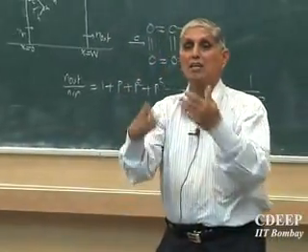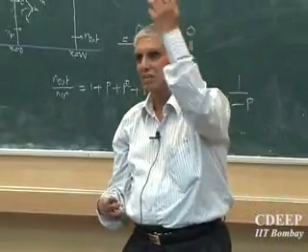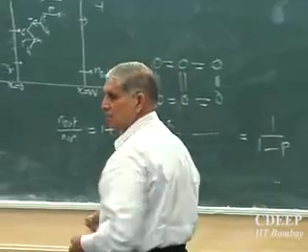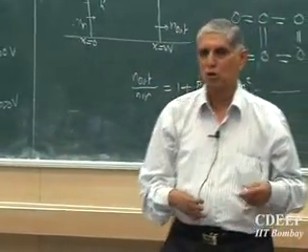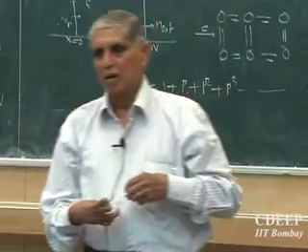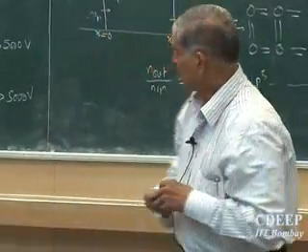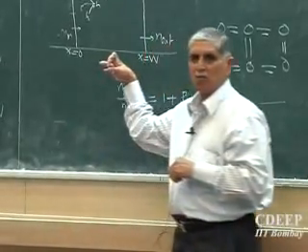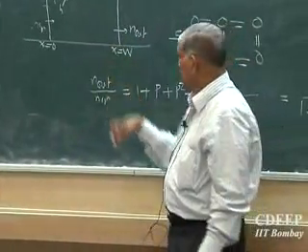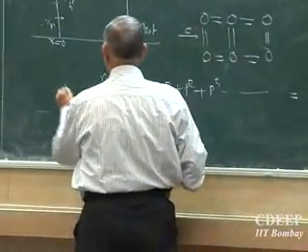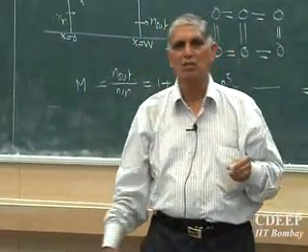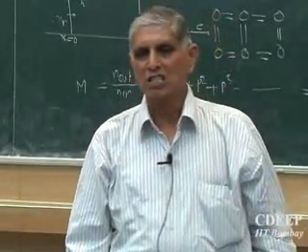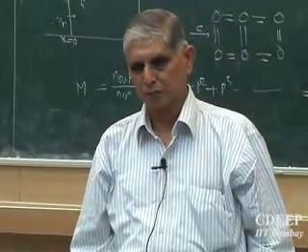Each EHP can then create more EHPs, and EHPs can create more and more and lead to what we call an avalanche of carriers, and therefore the breakdown mechanism was called avalanche breakdown. Details you can read in the other book. This is the theory which leads to this. Typically this factor is called M, the avalanche multiplication factor, and if M tends to infinity, we say a large current will start flowing.